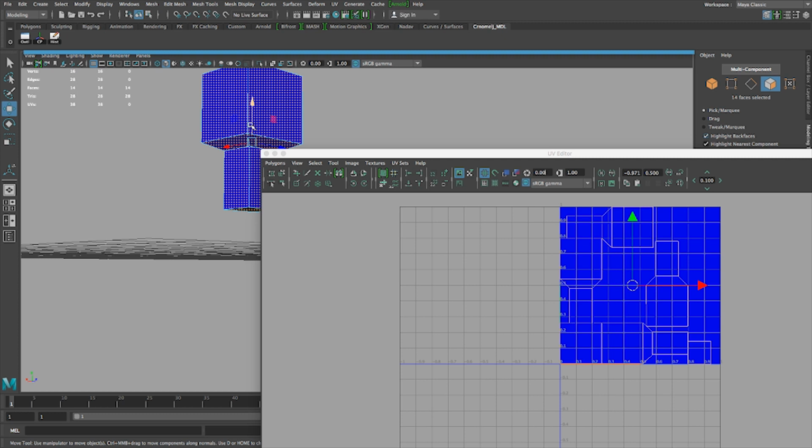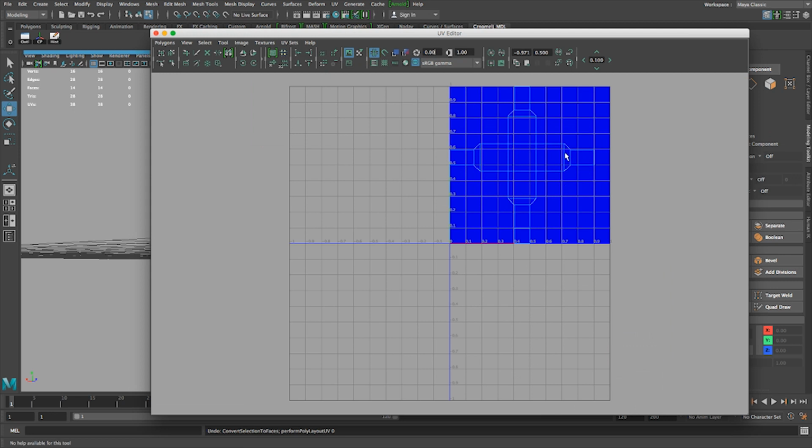And I'm going to go now undo. Since I have now, this is called a shell. A shell is one thing that's connected together. I have now one shell. Usually when you do UVs in the church, when we'll do Sveti Duh, we're going to have like 5 shells. One for the windows, one for the rooftop, one for the church tower. And we will choose where to connect them or disconnect them where nobody sees them. So it could be in exactly the point where the roof meets.